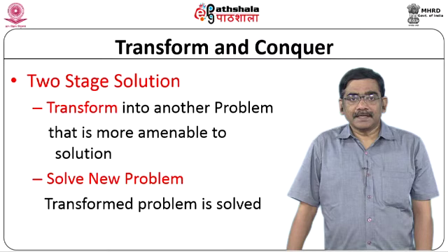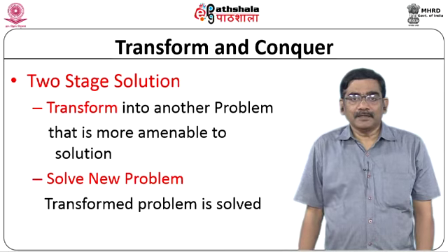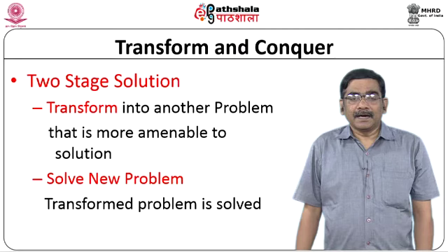You can see that in the last module we used the FFT to transform the problem from the spatial domain to the frequency domain, and in the frequency domain the convolution problem is reduced to plain multiplication, and after performing the multiplication we used the inverse FFT to get back the convolution of the original signals in the spatial domain.